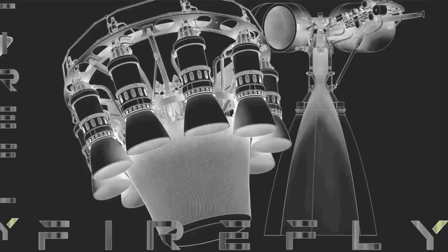And just like cold gas thrusters or any of the pressure-fed systems, at some point the trade-offs of getting a higher pressure in the system increases the weight so much that it's just not worth it. In fact, a fully and only pressure-fed rocket has never made it to orbit. So in other words, if you had your booster and your upper stages all pressure fed, none of them have ever made it to orbit. By most conventions, even with lightweight carbon composite tanks and other new age tricks, it's considered basically impossible due to its limited overall performance. But one company did have a solution.